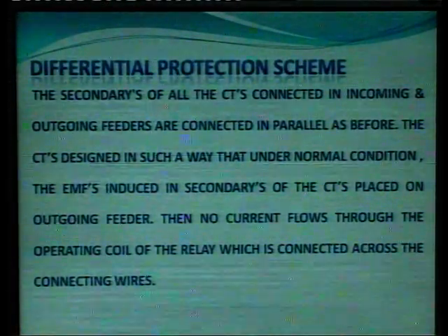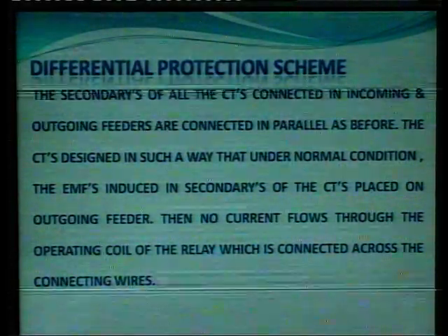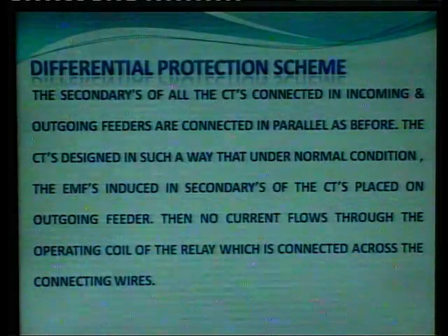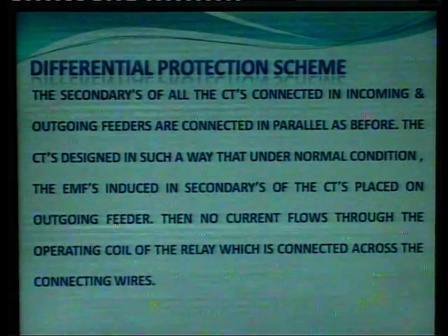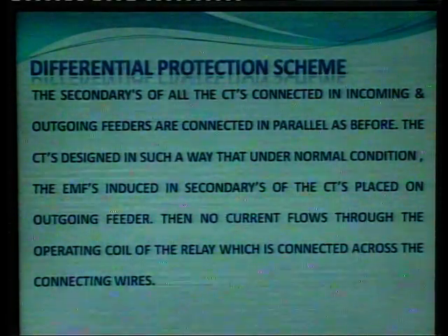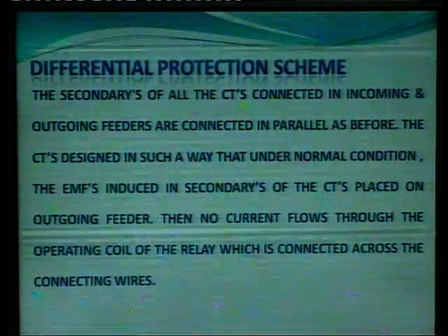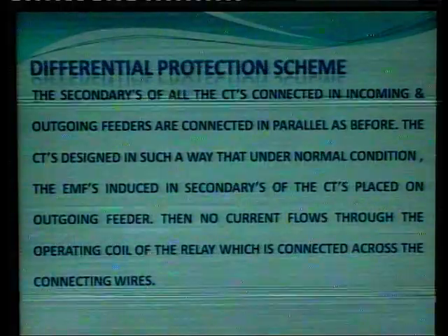parallel as before. The CT is designed in such a way that under normal condition, the EMF induced in the secondary of the CTs is equal to that of the CTs placed on the outgoing feeder. Then no current flows through the operating coil of the relay, which is connected across the connecting wire.